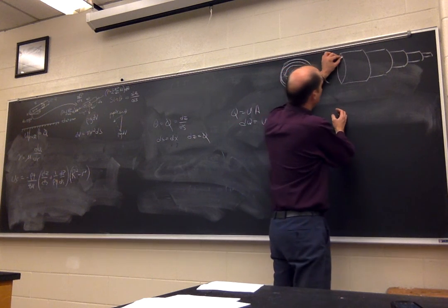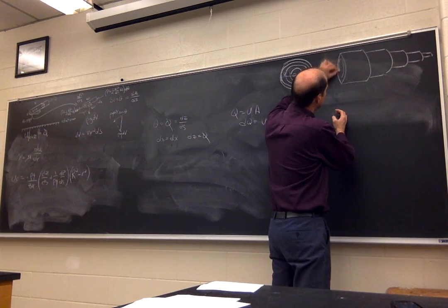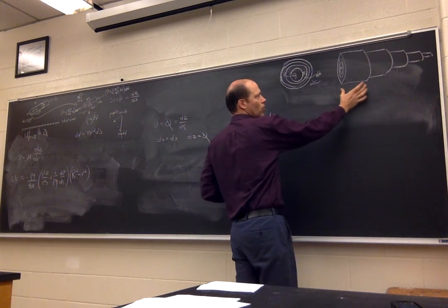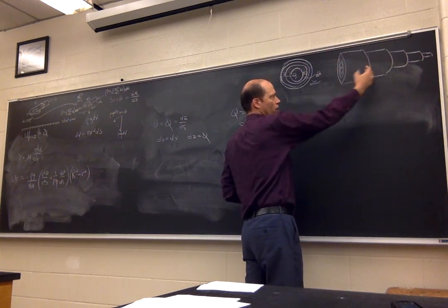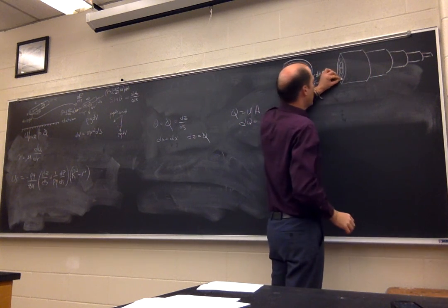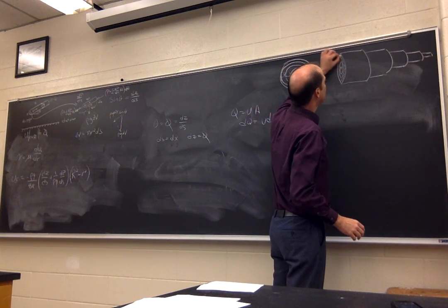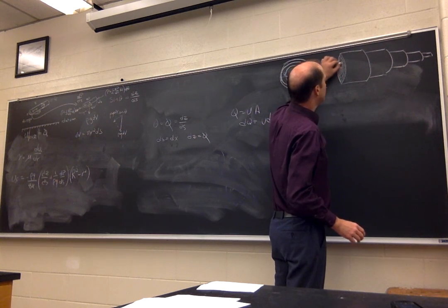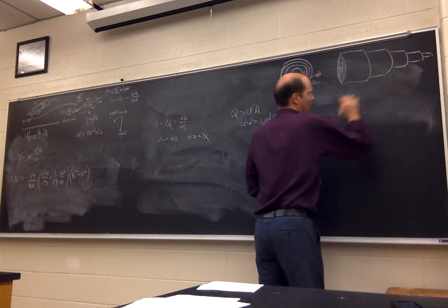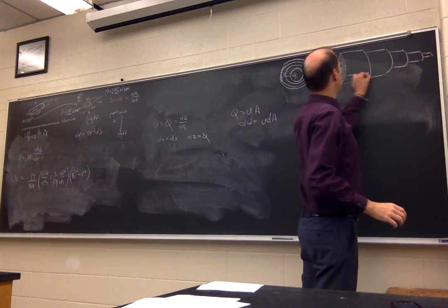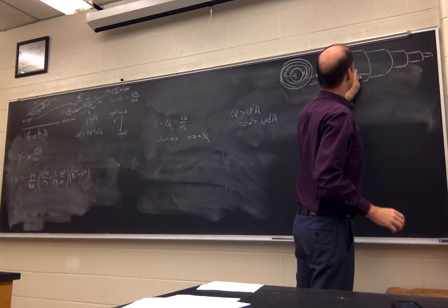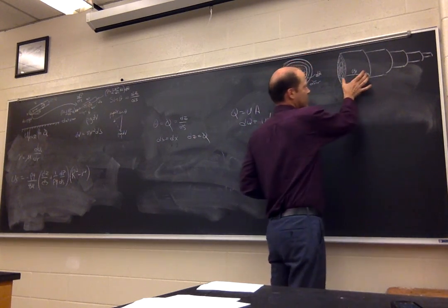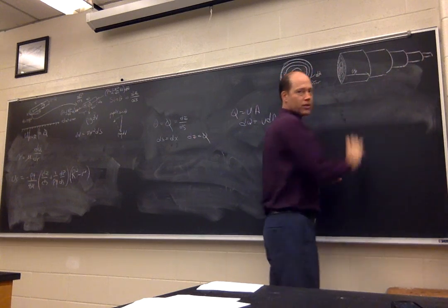I'm going to be looking at each of these little cylindrical slices, almost like a child's toy where they nest inside of each other, where I'm going to add up the velocity or the discharge in that little piece, and then each of these subsequent pieces with the velocity of each of these. So u sub x now, because we're considering it in the x direction since it's horizontal, u sub x is increasing as we move towards the center of the pipe.